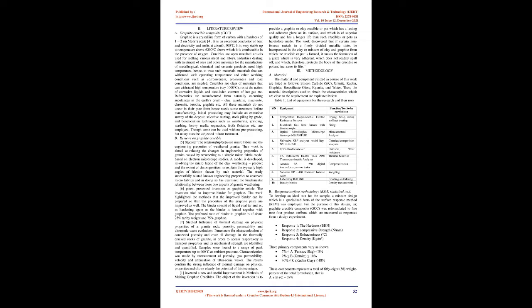For a material to be applied in crucible production, it must possess certain thermal, mechanical, and chemical properties. The material must have a higher melting point than that of the metal being melted, and it must have good strength even when the metal is white hot. Graphite crucible must also be able to withstand chemical corrosion and thermal shock. Although graphite and glassy carbon are commonly used as crucible material, when evaporating a carbon reactive material from such a crucible, a carbide layer is formed.